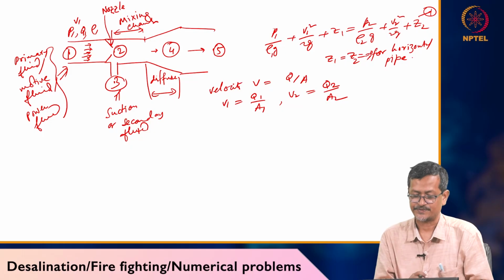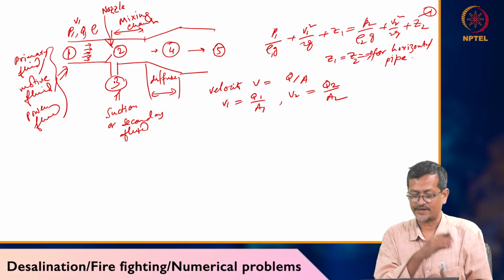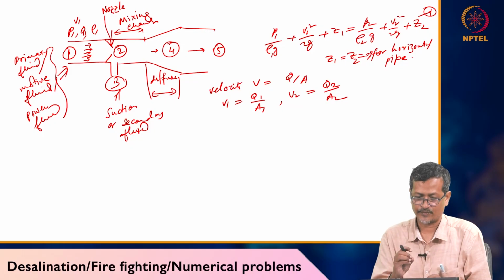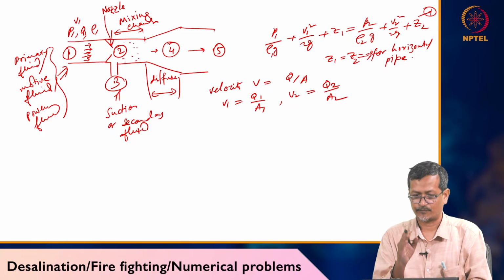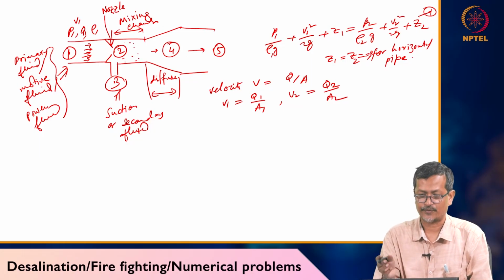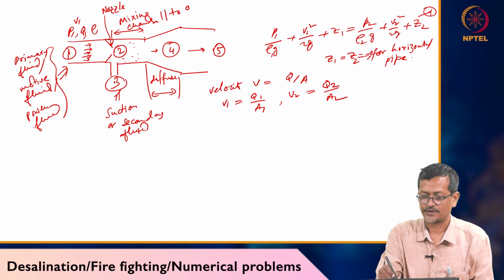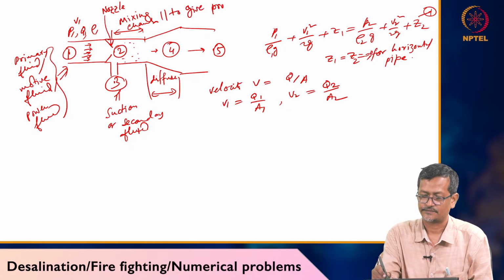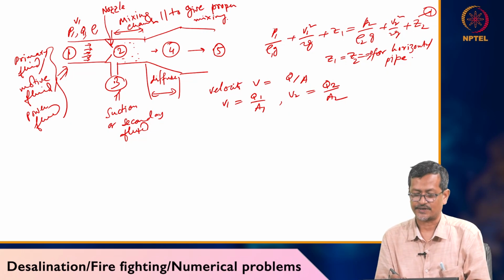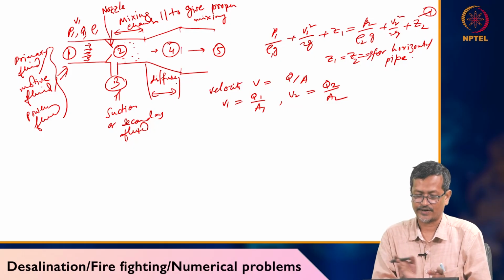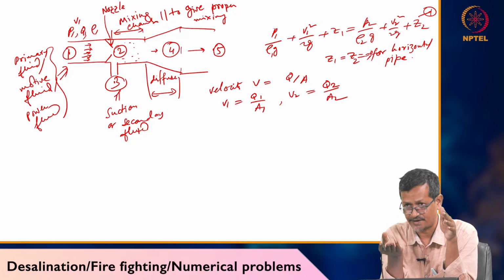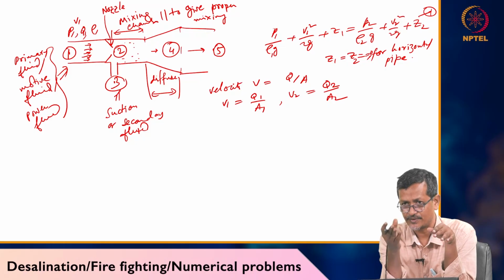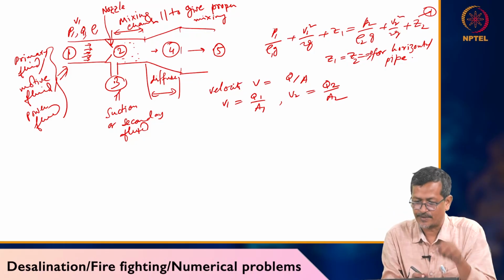Now the purpose of the mixing chamber: it mixes the primary fluid and the secondary fluid. The fluid coming from 1 and the fluid coming from 2 will be mixed properly in the mixing chamber. If mixing is not proper, your performance will decrease, so proper mixing is important. And what is the purpose of the diffuser? I have written that it is a wider section. A wider section reduces fluid velocity and increases static head. Kinetic head will be converted into static head at the diffuser.